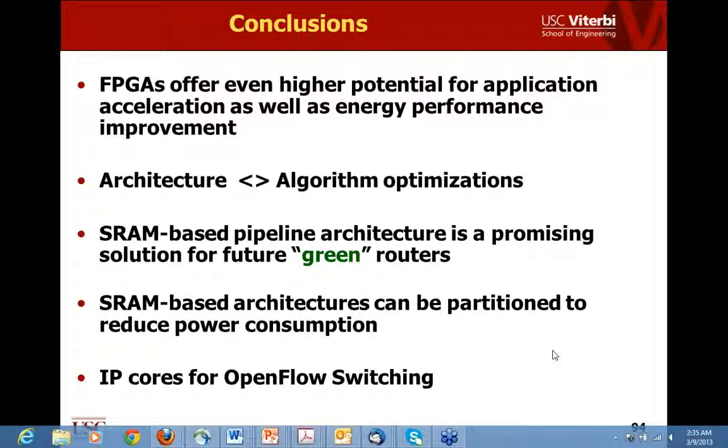But that is not the only model. For example, you may feel that if a signal goes through k number of gates, the delay should be somehow related to k. For example, there are what are called logarithmic delay models. The basic assumption there is that if you go through k switches, your delay is proportional to log k. So you can scale these results accordingly from that perspective. There are results of that nature also in the literature talking about variations of this basic model, where the delays are explicitly modeled and you get different performance numbers, and then obviously you cannot get constant time results as I showed here if you assume longer delays for those paths.